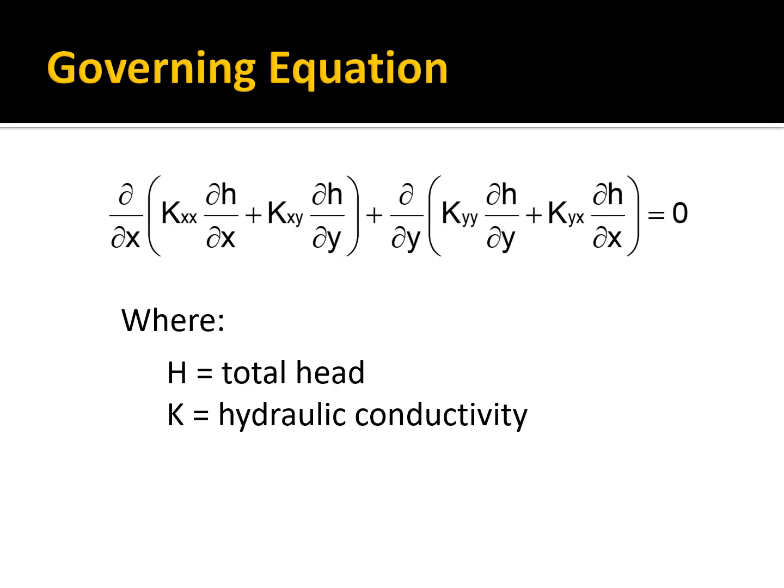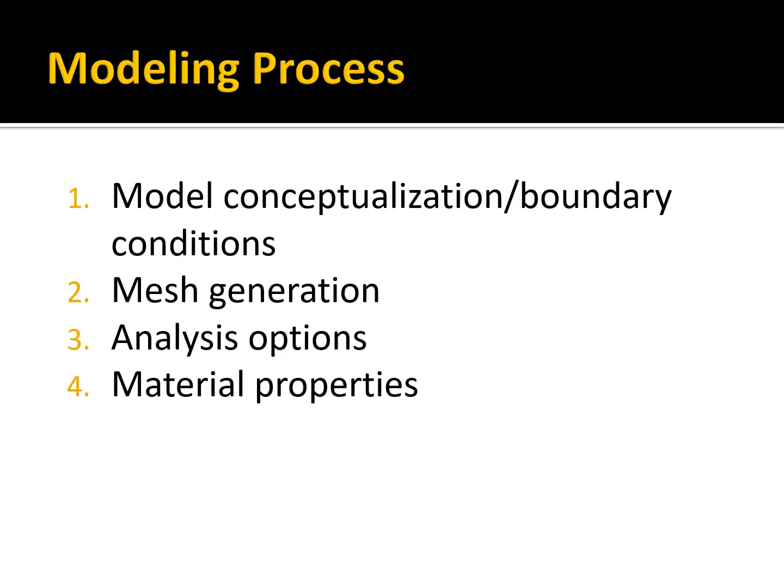All right, the governing equation used by seep2d is shown here. The right side is 0, so that means we don't simulate internal sources and sinks, nor do we have transient terms; it's steady state. And since we have kxy and kyx, that means that the principal axes of hydraulic conductivity do not need to correspond to the x and y directions, or as you can simulate the full hydraulic conductivity tensor. We'll talk more about that later.